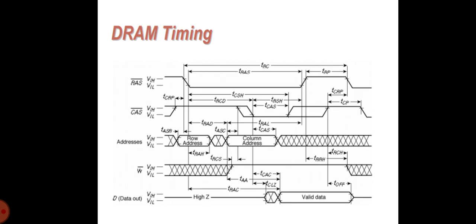Consider, for example, an RDRAM, where input-output data is transferred serially on a narrow bus taking several clock cycles. The bus is operated at a very high speed, however, and uses efficient packet protocols. Thus, a large amount of data can be transferred in a very short period. Multiple memory chips can be connected to the bus, called the RAM bus channel, and you can see the schematic diagram of the input-output circuitry of the RDRAM memory.